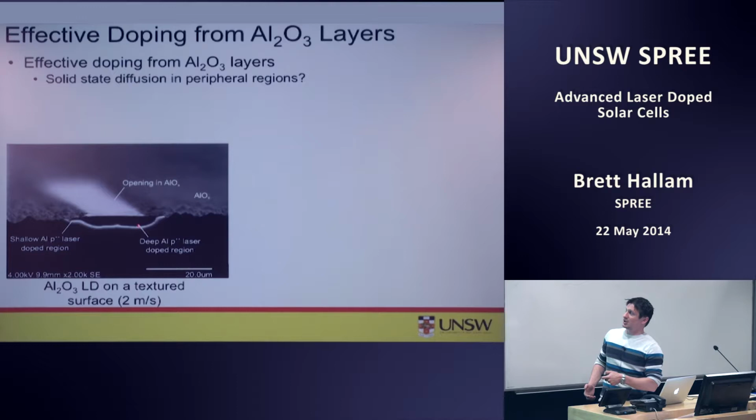As we go to the edge, it has this semicircular shape as occurs for the other dopant processes from the EBIC process I showed earlier. But there's an extra little kink in this cross-sectional profile at the very edges, and that would suggest that there's a second mechanism of diffusion taking place, and it may be that there's actually solid state diffusion occurring, which will have a diffusion coefficient many orders of magnitude lower than the liquid state, to result in this second part here.